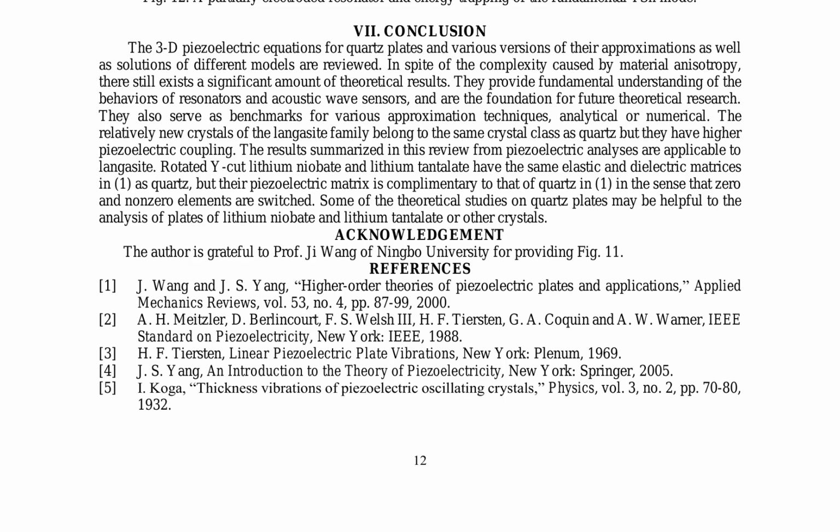A solution to the equation in terms of trigonometric series for a partially electroded resonator is also given, showing the energy trapping effect of the electrodes. Finally, the paper concludes that the 3D piezoelectric equations for quartz plates and various versions of their approximations, as well as solutions of different models, provide fundamental understanding of the behaviors of resonators and acoustic wave sensors. These results are applicable to langasite and other crystals, and serve as benchmarks for various approximation techniques, analytical or numerical.